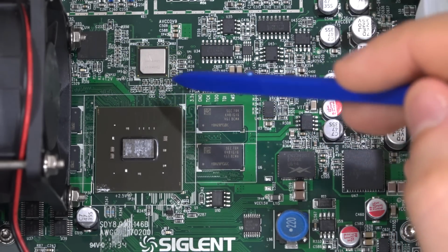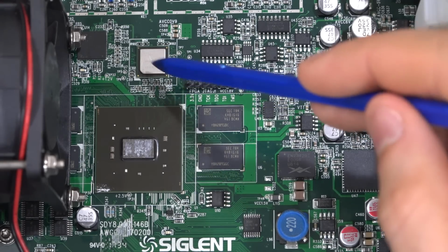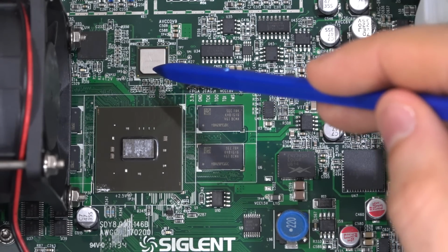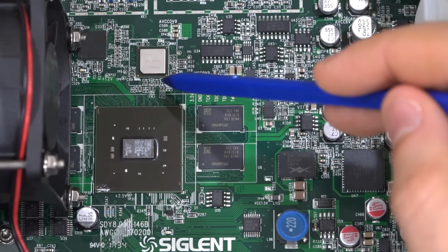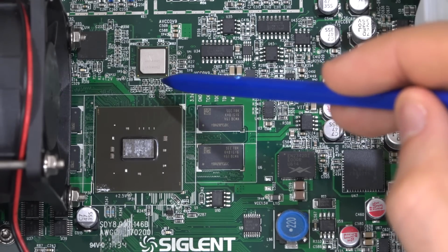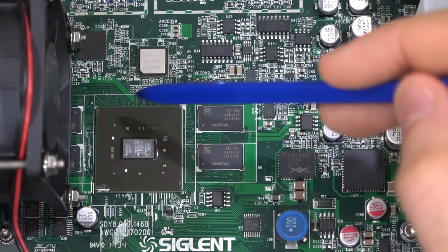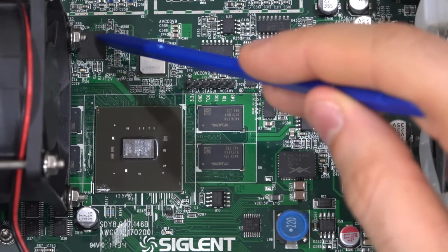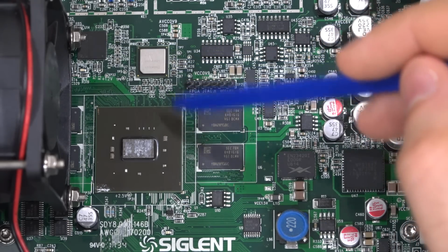And this creates a synchronization between everything, which is critical if you want to make sure that your DAC provides outputs in a synchronous fashion without missing samples, without having glitches or edge errors and so on. This is one of the things they've done really well in this design. That's why they can give you very low jitter in some of the waveforms they're generating. So we'll take a look at that as well. Just keep in mind that this component feeds several other components over here, and it's not just for the DAC itself.